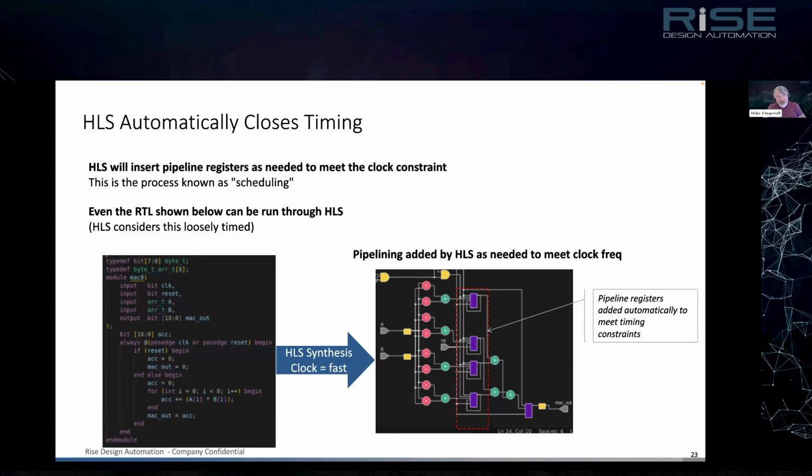High-level synthesis is going to insert pipeline registers to meet your clock frequency constraint based on the technology that you're targeting. So it understands the speed of the various operations, the multipliers, the adders, AND gates, and OR gates. And this is what's known as scheduling.